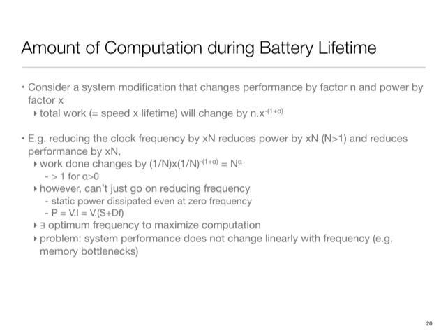Additionally, the complication comes as system performance does not change linearly with frequency. As I change the speed of the processor, its impact on performance in terms of speed is not simply by a factor of n, because caches and all those kinds of things complicate that part. And also not everything in the system changes when I change the clock frequency, because systems depend upon I/O interfaces, and I/O interfaces operate at some rate which is independent of the system clock frequency.